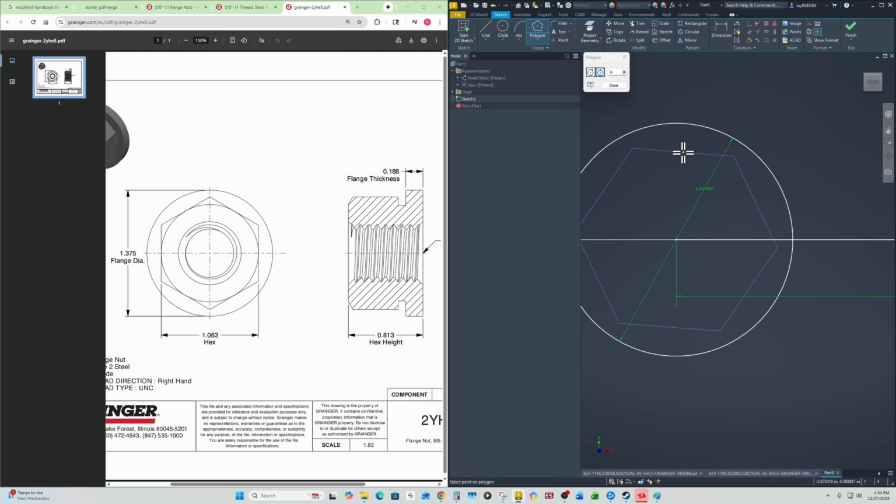Left click on the center, and then left click once. Make sure it also references the center this way. Make sure the purple dotted line also references once you go all the way up and see this reference. Once the icon shows up and the purple dotted line shows up, you should be good to go. So I'm gonna left click, then escape, then circle again on the center of it, and then see what the minimum distance is. 1.227.